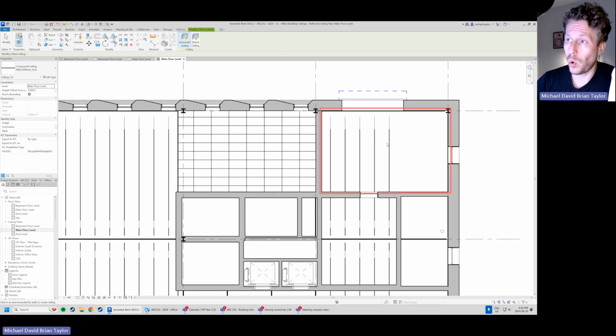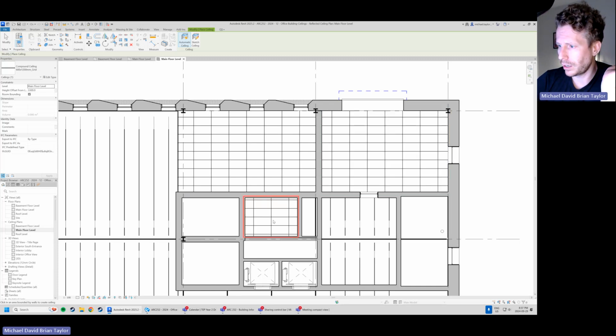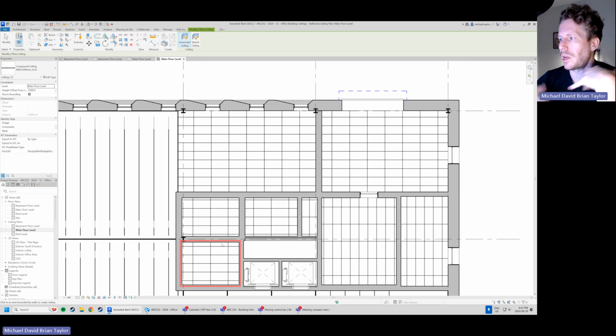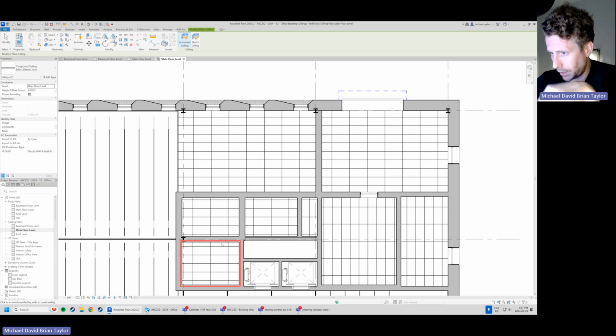And this is a very quick way to automatically assign ceilings in rooms that have closed boundaries. So you can just jump across and select any number of these. And you can see how I'm just kind of hovering, and then I click, right? Magical. Right, so now I've got all these ceilings everywhere. That is an automatic ceiling. So what it's doing is it's giving us, again, back to the idea of the room boundary, and then it's generating the ceiling from that.